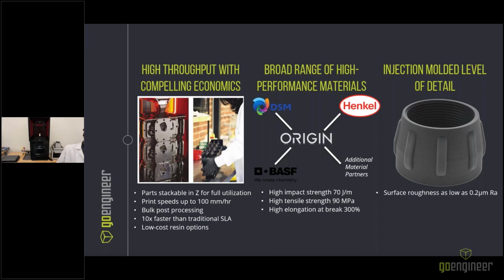The average surface roughness is about 1 micron, but with tuning, you can easily get this to less than 1 micron. Tolerances as tight as 1/1000th of an inch. And large solid objects can be printed without fear of warp or inaccuracies.